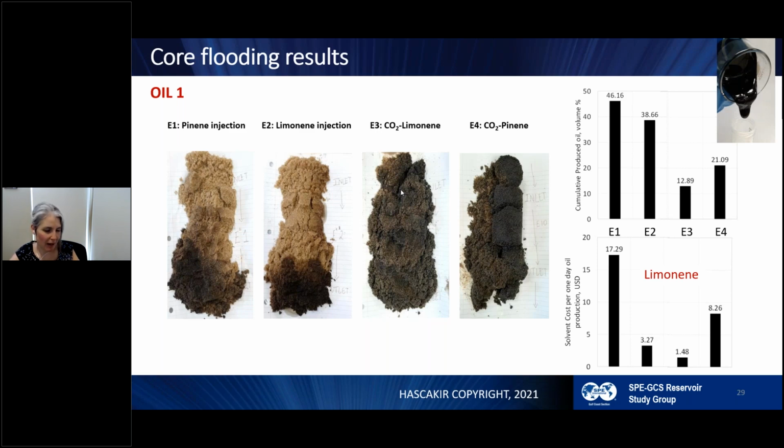It is extremely abundant. I am not sure if you are washing dishes. So I strongly recommend everybody to wash dishes. You will get a lot of tips about enhanced oil recovery. If you're dealing with a pan which is covered with oil, you may have different tactics to clean the oil. One of them is detergent, which we know as enhanced oil recovery, surfactant flooding. And the other one is putting some water and heating it up. And this is called hot water flooding in the EOR, or steam flooding in the EOR.